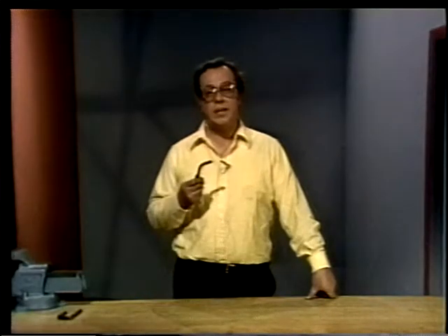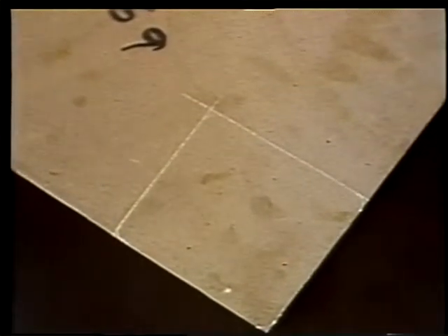Now that we've seen what annealing did to this pin, let's look at a typical example of the use of annealing in the shop to make metal easier to work with. This sheet of copper is used as gasket material. A pattern has been laid out, and it has to be cut to size. Without annealing, this would be a hard cut to make. After the piece is annealed, though, it can be done rather easily.